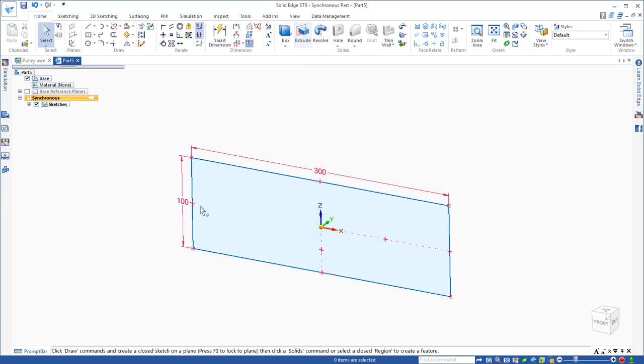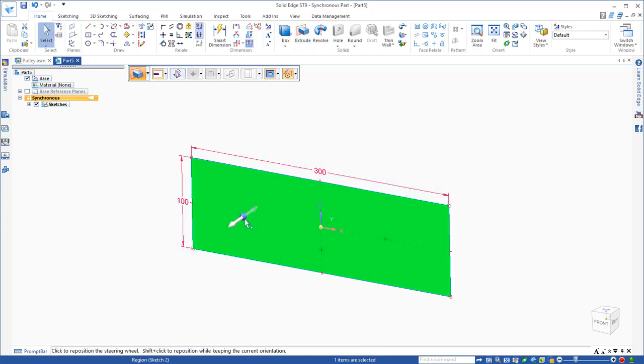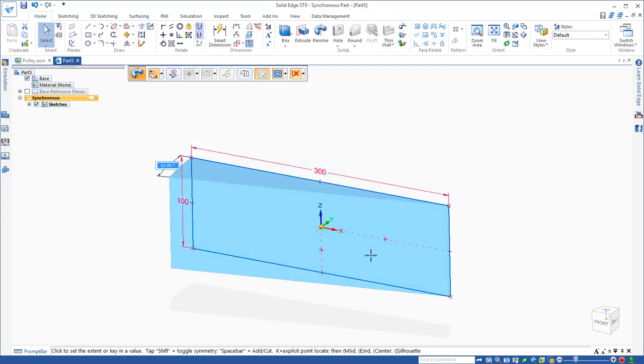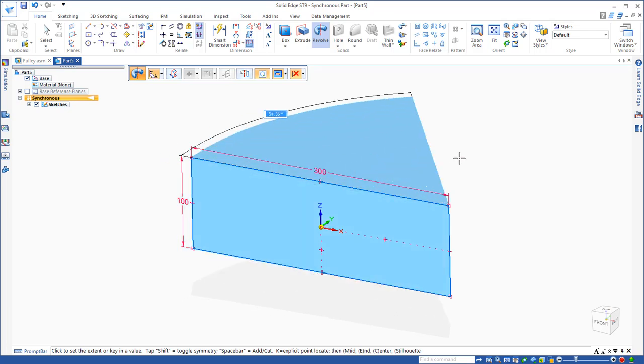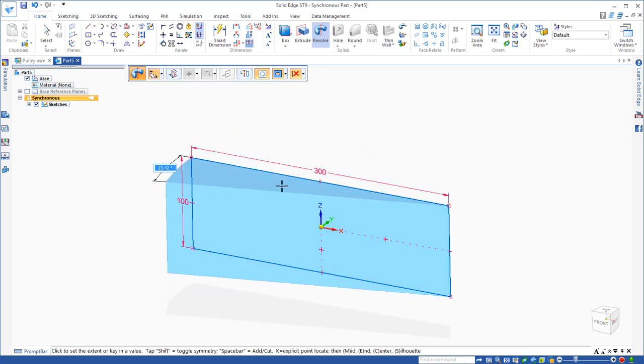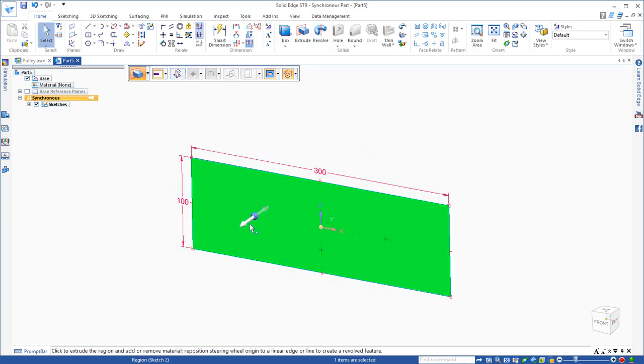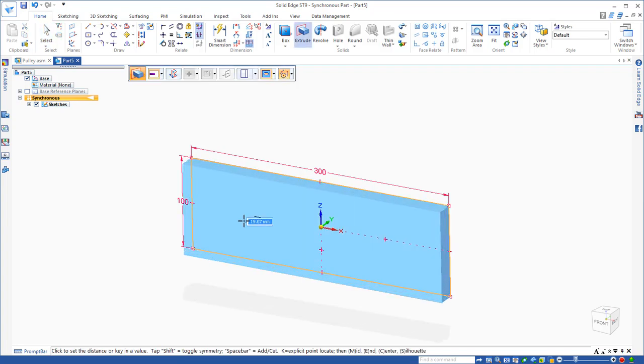Okay. The other thing I could do is I could drag that origin to an edge. What that does is allow me actually to go into a revolved extrusion, again, without having to actually pick a command. Our case, we do want to just do an extrude.